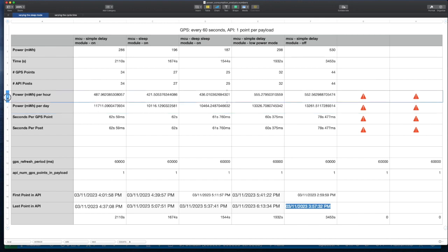If we look at the lowest number, here's delay, MCU delay, had this number. I put it in low power sleep mode. It did go down a bit, not a lot, and we'll talk about why this didn't go down a lot in a second. And then deep sleep mode, you can see it actually increased a little bit. I think this is probably within my noise margin, and I wouldn't worry about that too much.